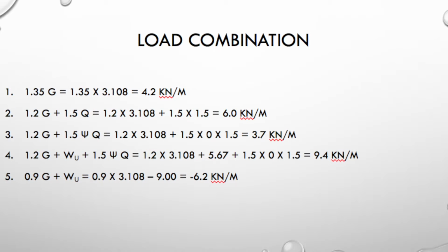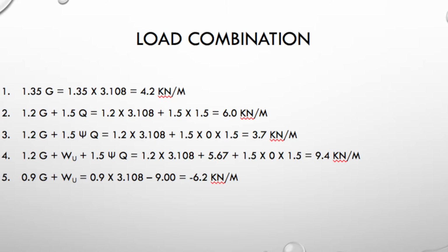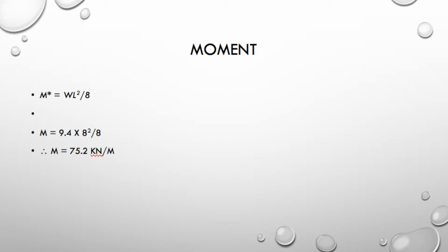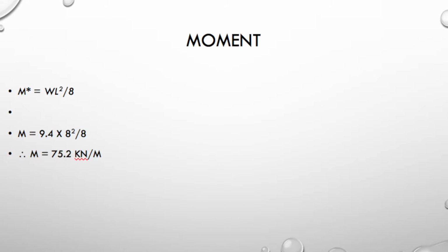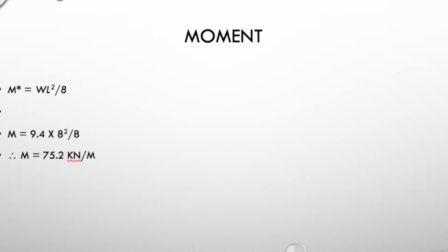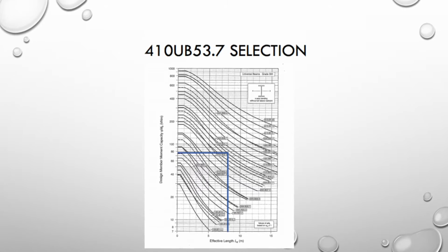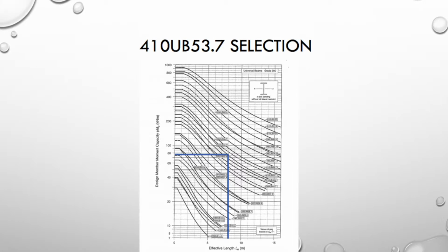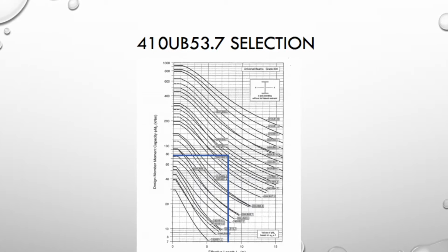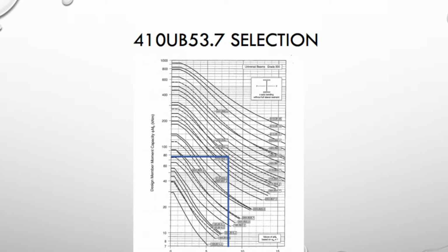The design capacity tables provide structural engineers with the ability to select structural support members that are both safe and economical. By choosing the rafter member that intersects the line given the moment capacity and effective length, the suggested beam will be strong enough to support the structure without being unnecessarily strong. This process is then repeated for the end rafters, as they will be different to the central rafters. One of the key findings was that the central and end rafters will in fact be different, despite the fact that we initially thought that they may not be.